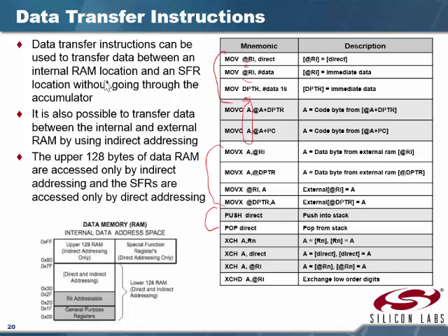The next three are fairly obvious. All they do is exchange two locations with the accumulator. They just swap the data. Whatever's in the accumulator is moved to the register. Whatever's in the register is moved back. That's why that temp register is needed. There's that buffer right there.